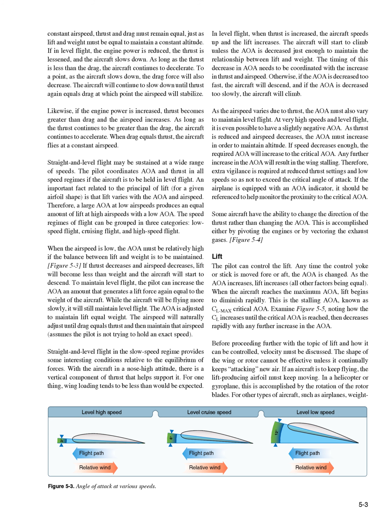As long as the thrust is less than the drag, the aircraft continues to decelerate. To a point, as the aircraft slows down, the drag force will also decrease. The aircraft will continue to slow down until thrust again equals drag, at which point the airspeed will stabilize.